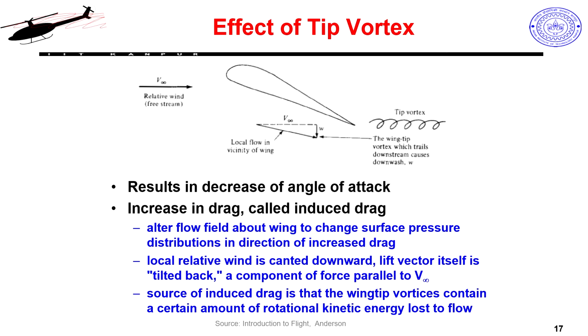So, this is something which happens pretty close to the wing. I believe I have earlier drawn this kind of diagram where, if I look at half wing, this is my half wing, my lift distribution, sorry, I should have drawn it all the way here. The lift distribution would look somewhat like this, which means near the tip it will go down to 0, and that is actually done by this tip vortex effect. So, what tip vortex does is that it induces this downward component.